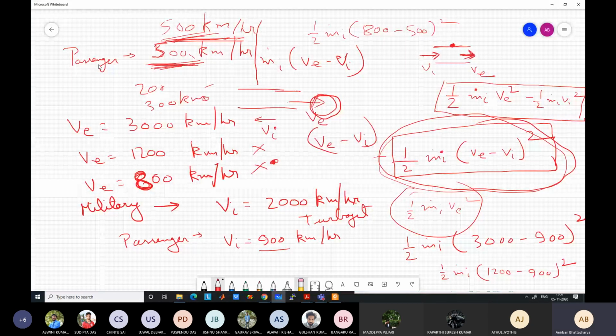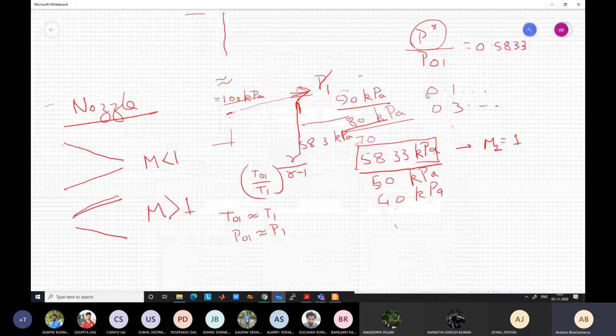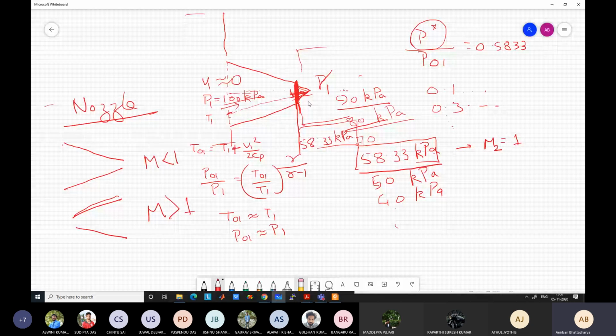If the nozzle is convergent, it only decreases in area. So at some ambient pressure on the outside, the nozzle will become choked, which means that the velocity at the outlet section will become equal to the speed of sound.